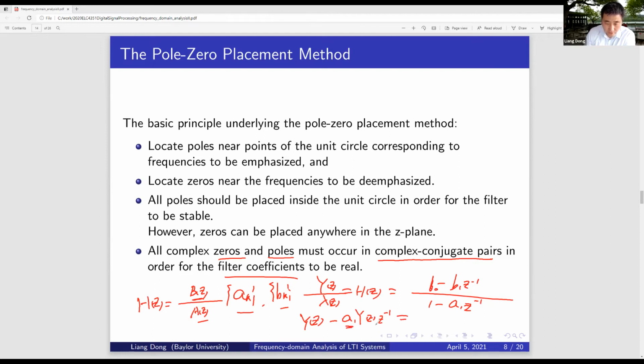This is the coefficient of this delay unit. Let me just look at this part. This part is a feedback. I'm going to feed back with a z to the power -1, taking the y[n] in the time domain, and that gives me y[n-1]. But you also want to give a gain to this feedback loop. The gain is a real gain, so it's A1.